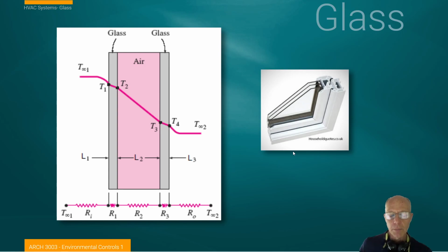I didn't spend enough time discussing the insulating value of air. So I've shown you this graphic before to give you the idea that each layer creates a certain amount of insulation value. We have an exterior temperature, an interior temperature, and as it passes through each resistive element, the temperature decreases. I discussed that at some point there's a condensation layer that forms. But beyond that, this idea that air is an insulator is very important.